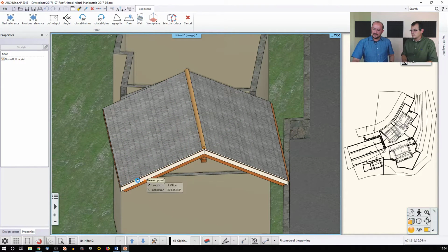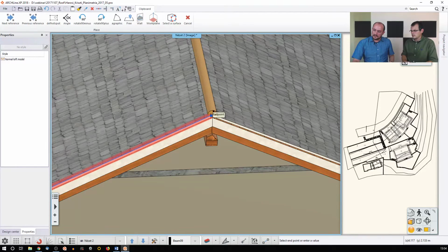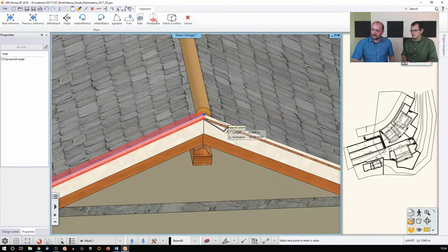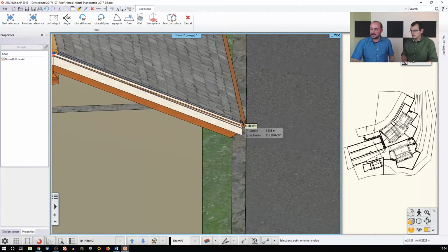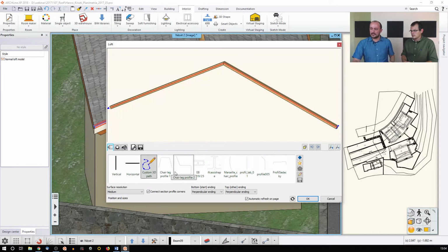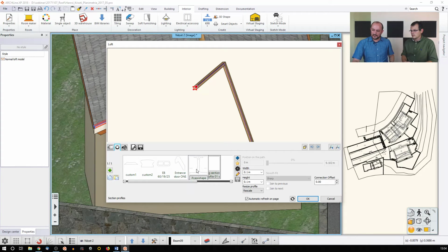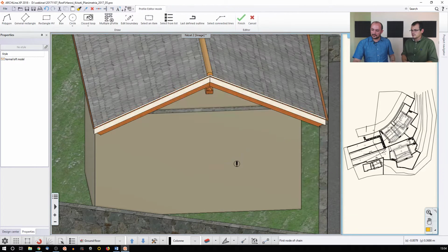surface, and then you can select edges. And the same thing happens when you are in an interior. You can just go and find the room contours and the window contour and so on. So this way you draft the path and you say, okay, I'm fine with that, but I'm not fine with the cross section. And the cross section is again something that you can set up here. You can select from a range of cross sections, or actually you can create your own cross section.